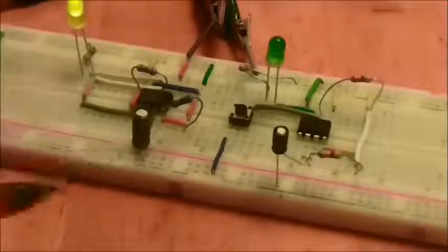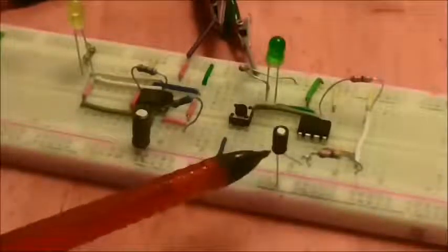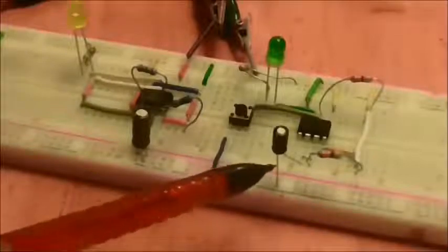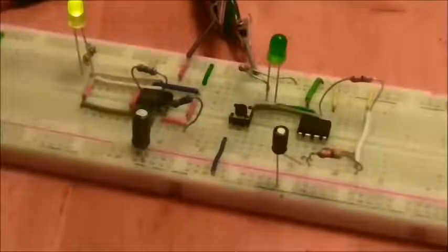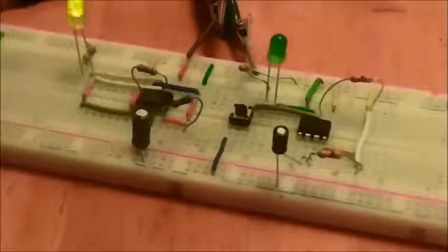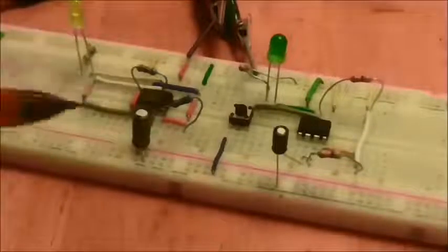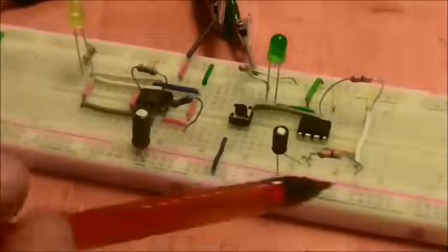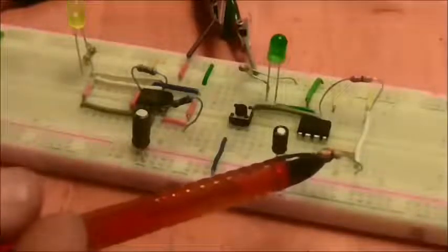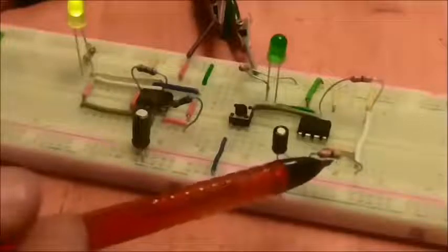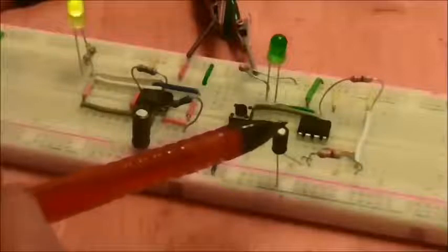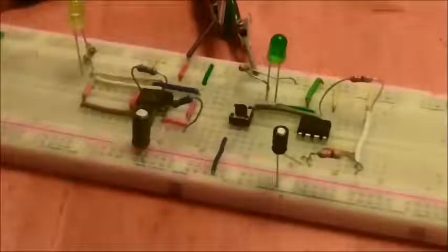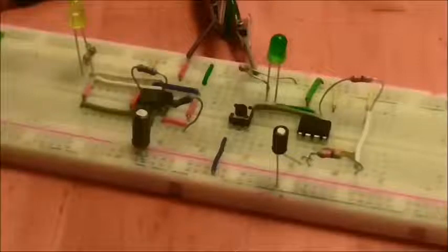Moving on to the monostable then, it's a little easier because we've only got one resistor and one capacitor. And to get the time that the monostable light is on, what we'll do is we say T equals 1.1 R1 C1. So we multiply R1 and C1 together. R1 is a 47k resistor, so that's 47,000. C1 is again a 10 microfarad capacitor, so 0.00001, and if we multiply those two together, what we should come up with is 0.47.